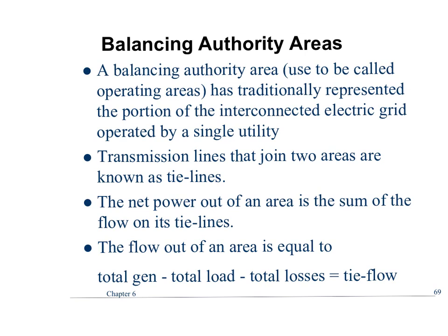A balancing authority, so we talk about we want to share, right, with our neighbors. So ISO New England is trying to get power from New York ISO when they need it. So if I can buy power from New York that's cheaper, or I can sell power to New York and make a profit, you can actually schedule the power in these interconnecting tie lines. The line between New York and ISO New England, or Hydro-Quebec and ISO New England, those all have to be for buying power. So the balancing authorities actually make sure that the power flow through those lines is what's agreed